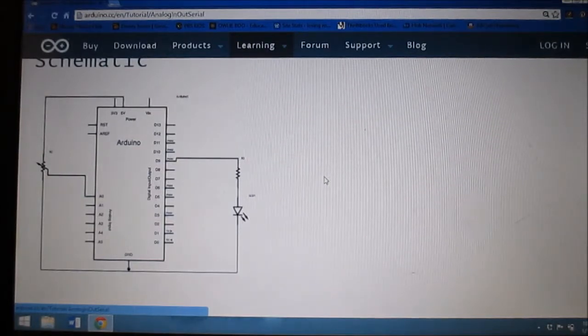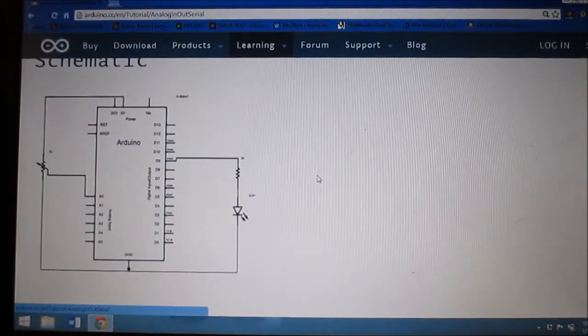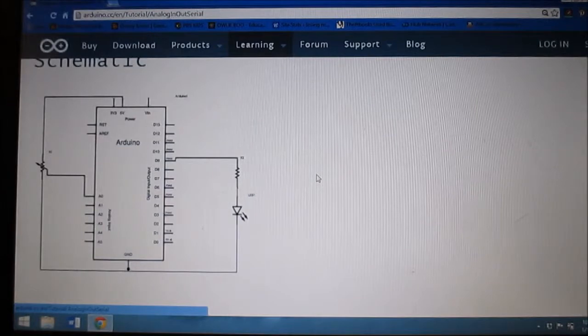In other words, if you have the square wave 50% on and 50% off, it'll be about a 50% duty cycle, which should send 50% of the available voltage to the light. If you have 10% on and 90% off, that's like a 10% duty cycle, and it should send about 1/10 of the voltage to the light, which would make it dim. But basically that's what pulse width modulation is.